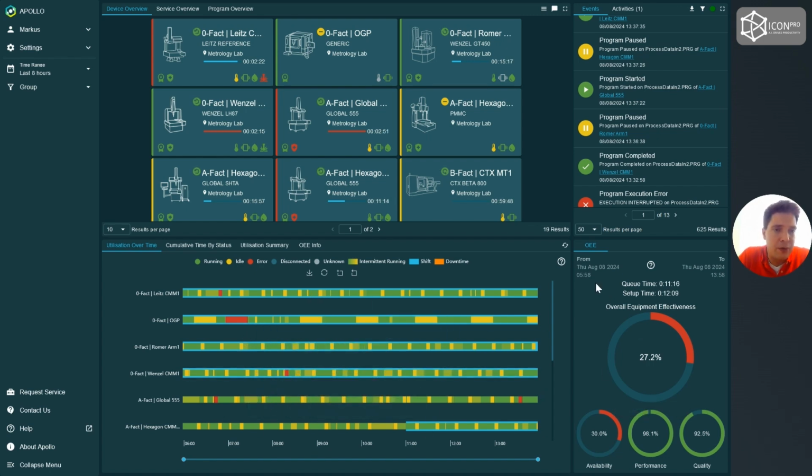On the bottom right, we see the summary of how effectively my machines are working. If I ask myself not only whether everything is fine, but how utilized my machines are, then I can quickly see this via the overall equipment effectiveness evaluation. Here it is 27%, which is not too good actually. And we can see that this is mainly due to one of the sub-parameters of the OEE, namely the availability. So here the OEE is not so good because of the availability being not so good.